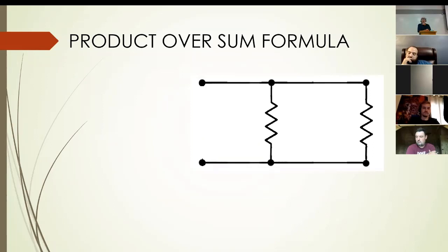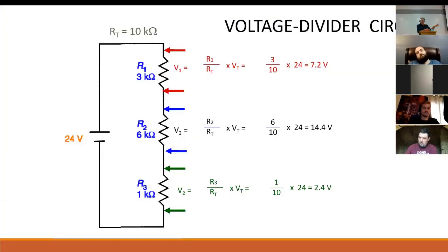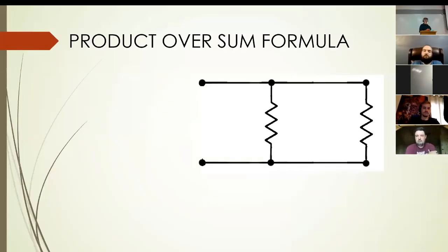All right, now we're looking at resistors in parallel. A little bit different, because total resistance, just for a second, going back to series resistors, whenever I combine the resistances, it's always going to be larger than the largest resistor. So whenever I combine resistors in series, the number I get is always going to be larger than the largest resistor in there. Now that should just make common sense. But I'm saying that because it doesn't happen with parallel.